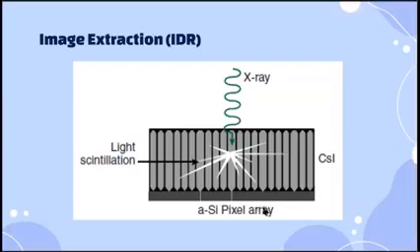So, since they are in amorphous silicon form, they become photodiodes. Okay, ang mga detector elements here, okay, so the detector elements will become photodiodes which convert the light produced here into an electrical charge. This charge is stored on a capacitor and released when the TFT gate opens for the DEXEL to be read out. So same lang sila nung direct radiography. Okay, when it comes to the detector element. Okay, but this time we are using amorphous silicon.